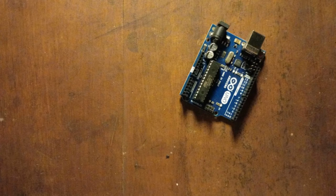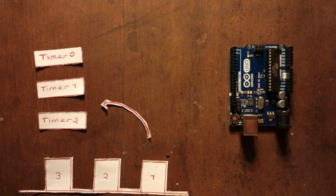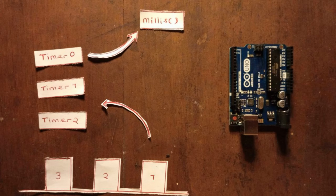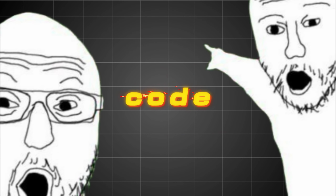Now, the Arduino UNO has 3 hardware timers built into it: timer 0, timer 1, and timer 2. Essentially, what these timers do is they count clock cycles. The millis function makes use of timer 0, keeping track of the elapsed time in milliseconds and returning that value to our code. Enough with the theory. Now let's jump into some code.